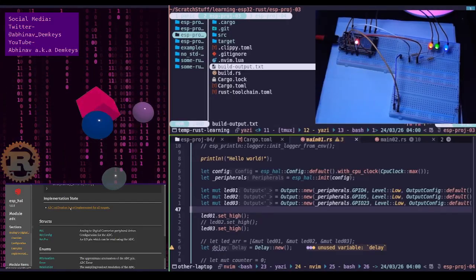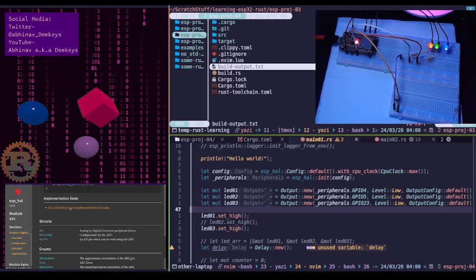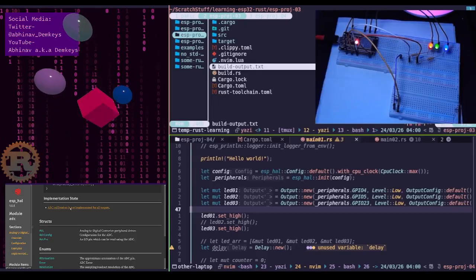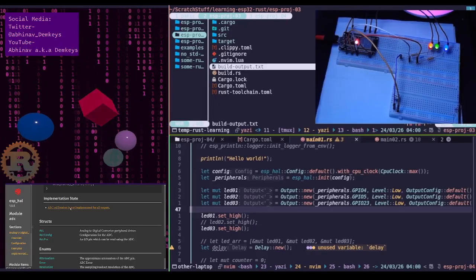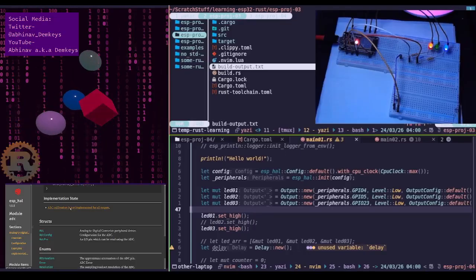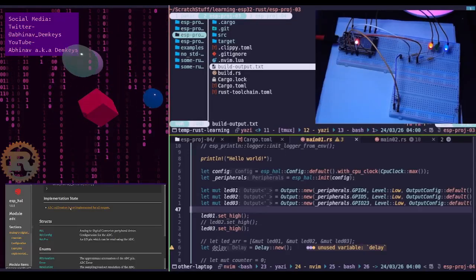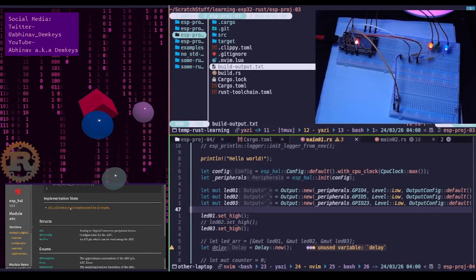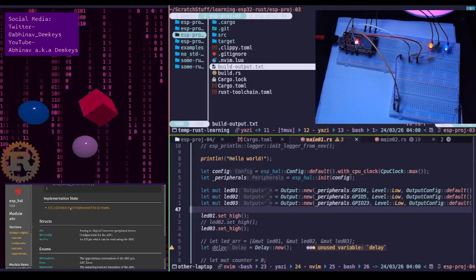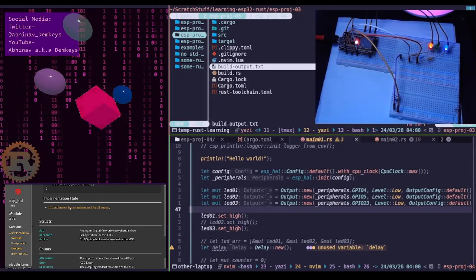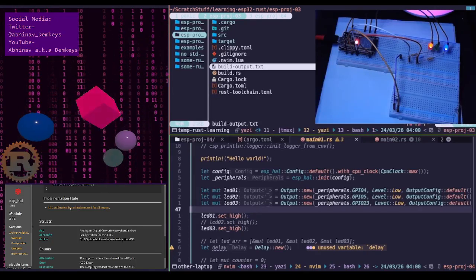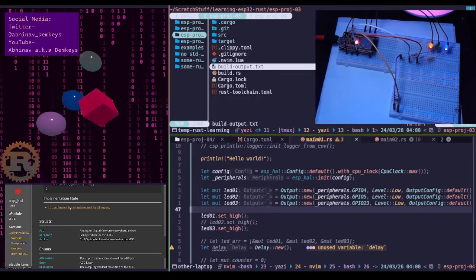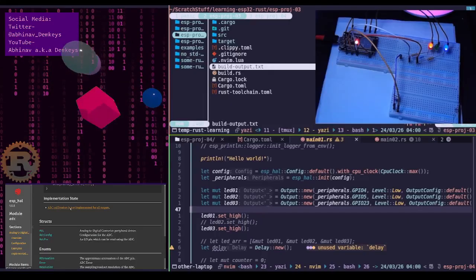When you read a value from an ADC, the chip converts a voltage into a number, which is 0 to 4095 for a 12-bit ADC. Ideally, 0 volts would always be 0, and 3.3 volts would always be 4095, but silicon isn't perfect. Okay, two types of errors. Without calibration, you will encounter two main issues.